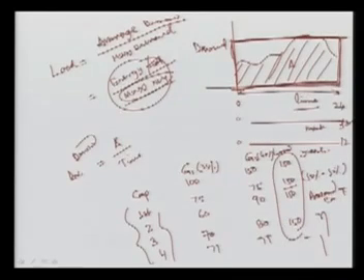Here we always try to go for economic dispatch, which means we have to run so that we can achieve the minimum cost. The cheaper generators will generate at 100% loading, and the others will be expensive, so they will be reduced. For example, let us suppose G1 is very cheap, so it will go for 100 megawatt and the remaining 50 will come from the expensive generator, so that we can achieve the minimum cost generation. That is the major criterion for this.